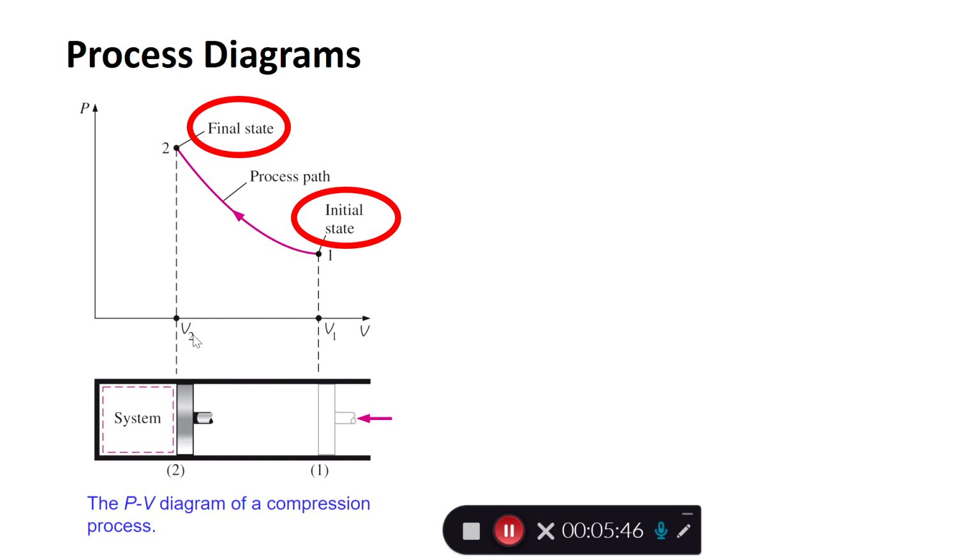State 2 has a reduced volume, right? Because you can see that inside is the system. The system is not the whole thing. It's whatever is in the closed compartment. So state 2 has small volume but high pressure. How do we know? Because of compression. Of course, when something is compressed and the mass doesn't go anywhere, it will increase in pressure. So this is an example.